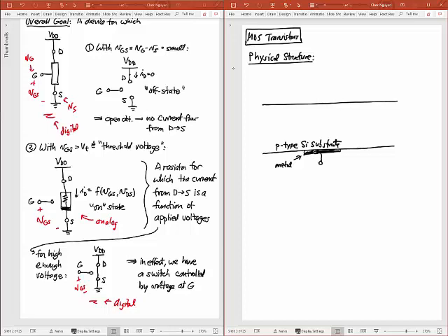And that then will become a terminal. And I'll call that my bulk terminal. So that stands for bulk in this. The voltage there I'll call VB. And I can have a current going in there, which I'll call IB. So I have this as a p-type substrate. I also can make this p minus too. So often you'll see that p minus, much more lightly doped than the other parts of this.